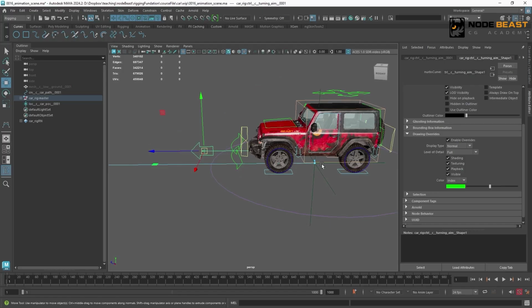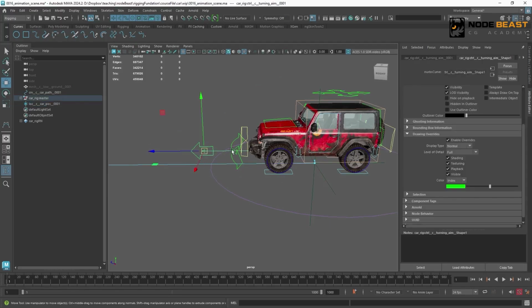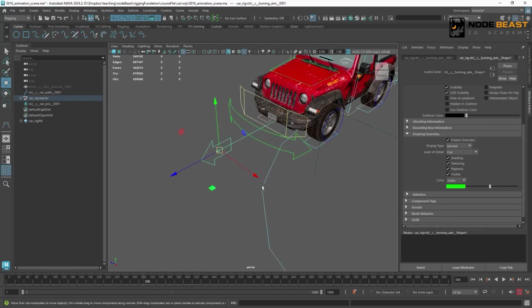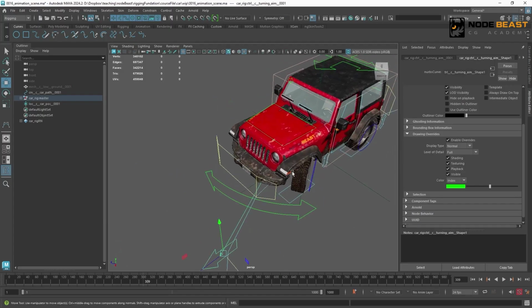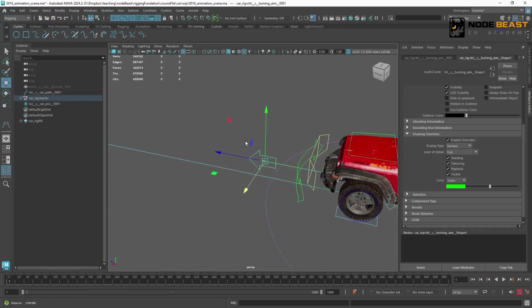When making the car move along the curve, we need to create another locator. Ensure it stays in front of the car's own locator. This way, it can always have a steering effect. For example, it's here now. If we set a locator in front to constrain this controller, the controller will be in this position. Look, at this time, the car already has a steering effect. Let's do it. The method here is the same as before.